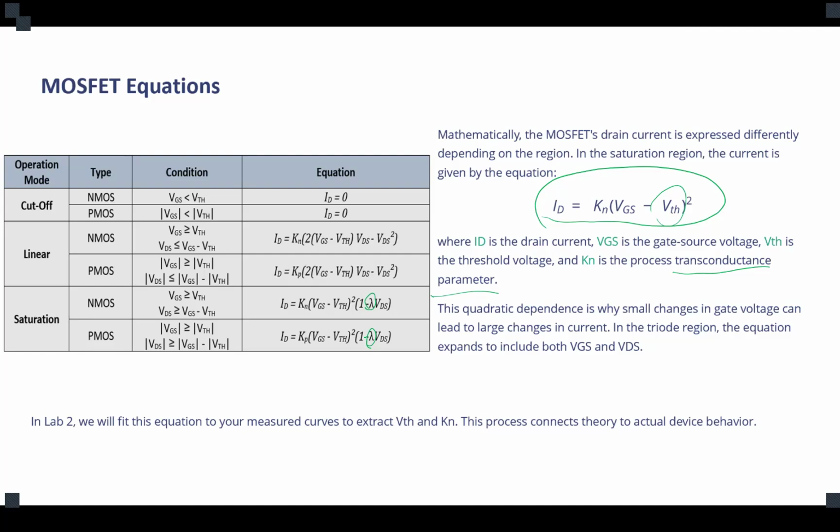But it's good to know that there is an effect of the width of the channel, the characteristic of that channel in the semiconductor, that would affect the current in a drain besides the voltage between gate and source. Are we good? So this is how you can calculate the current based on the VGS.